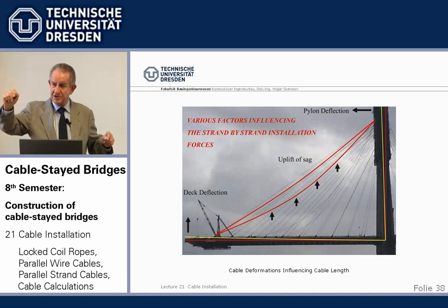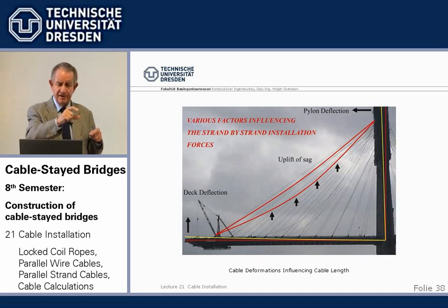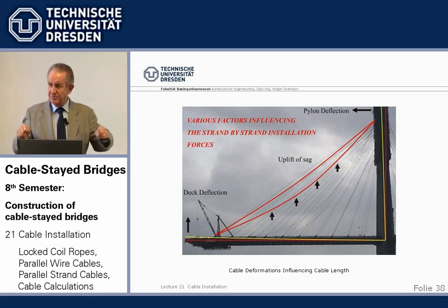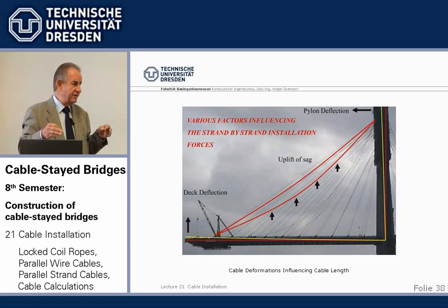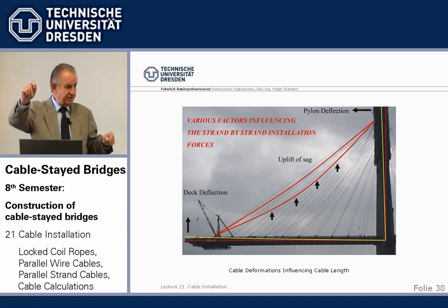When we have calculated that in this situation we need a shimpack 4 inch, 10 centimeters thick, then that's all you need, because you know you have the correct cable length. And as long as the beam is built correctly and the tower head and all that is very carefully surveyed, you can't go wrong. You must come out with the right structure, because the cable length is predetermined.